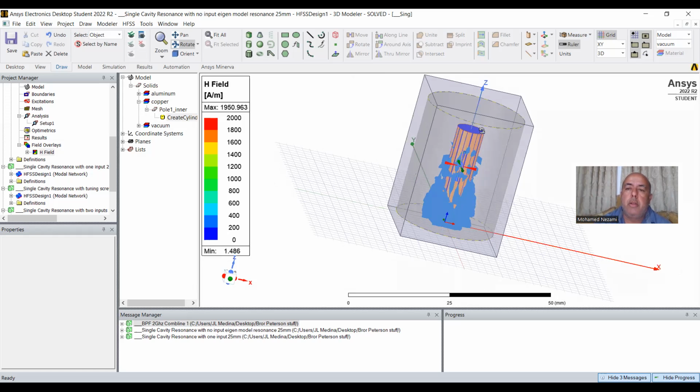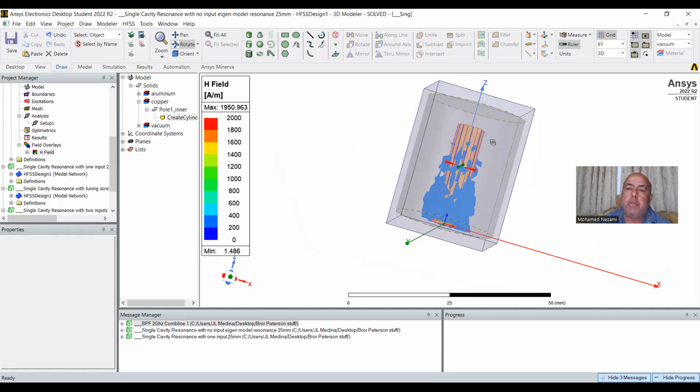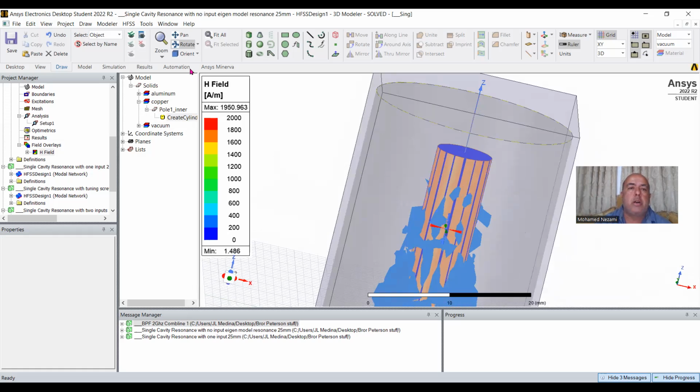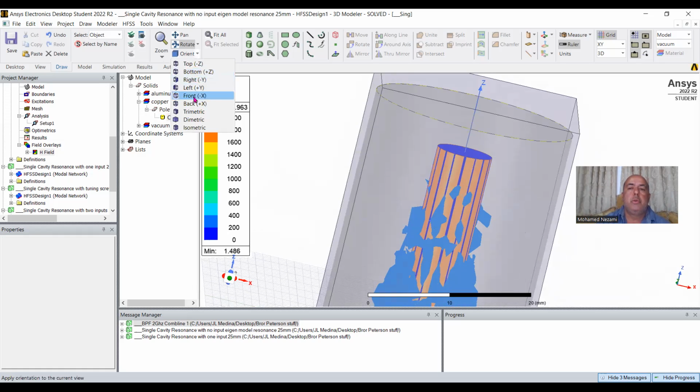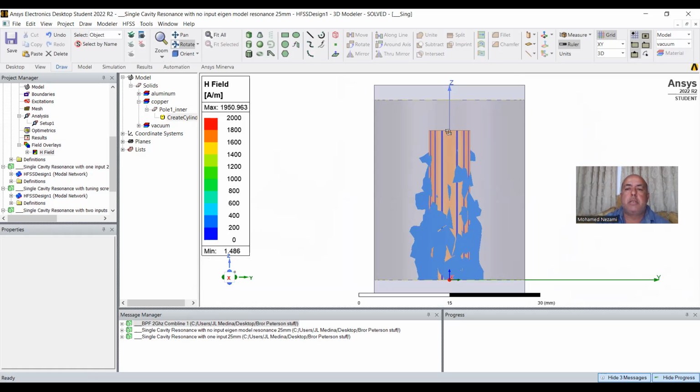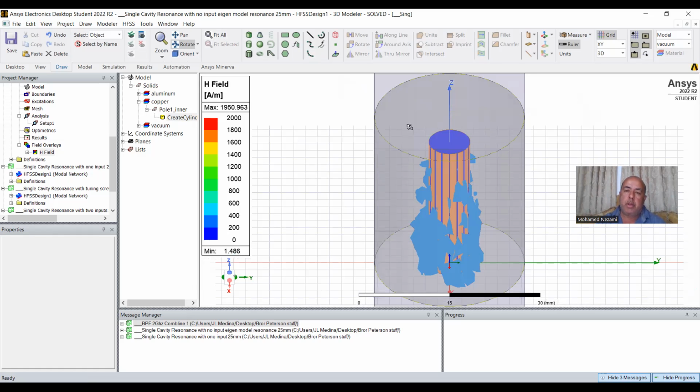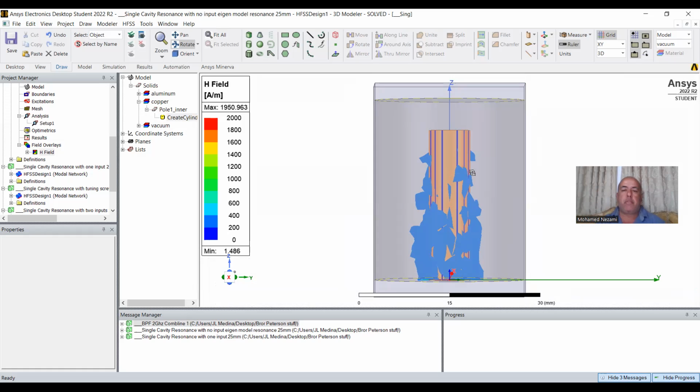It's purposely so, because we're going to introduce some capacitance. As you can see here, the distance is a large distance, so the capacitance in here is at minimum. If you introduce any kind of tuning metal in here, the overlap cross-section of that metal with the end of the resonator will act as a capacitor and will bring the frequency down. So we're going to use this as is, keeping in mind that this is really resonating at 2.4, and we know it's going to shift down. Hopefully that shift will bring it close to 2 gigahertz, okay? So let's go back to this.